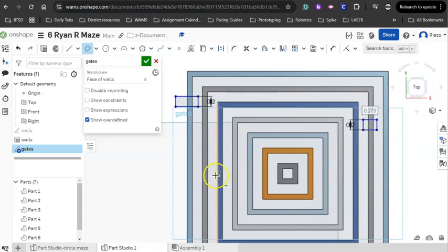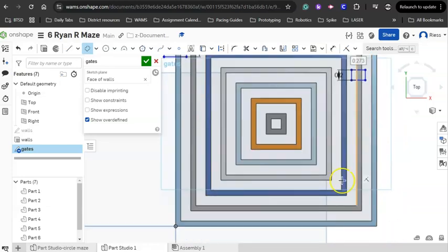And you certainly could just go through, and again, this should be done to your brainstorming sketch. You certainly could put all your gates in and then go back and dimension them. It's 0.2. Or as you're doing them, right? If you put your mouse right there, it would be that one. Put it over here. Now I can just start typing 0.2. And do the next one. Change it over here, 0.2.